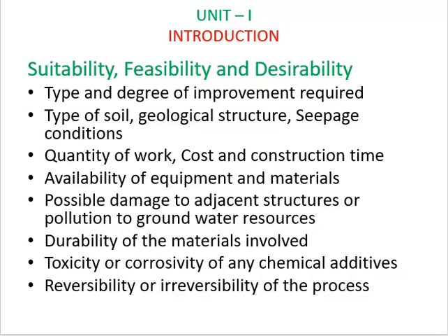The geological conditions like location of water table, different terrains at the site also influences the selection. The seepage is a biggest problem for earthen embankments, hence proper seepage analysis has to be done for preventing the seepage loss or failure.